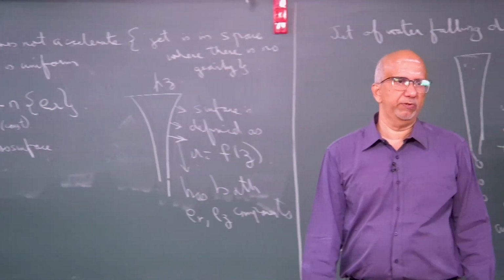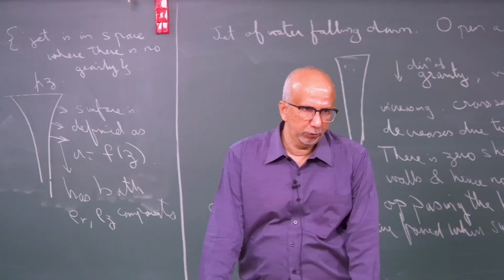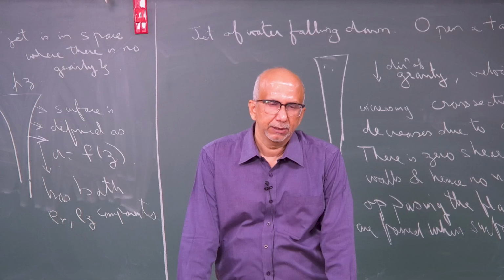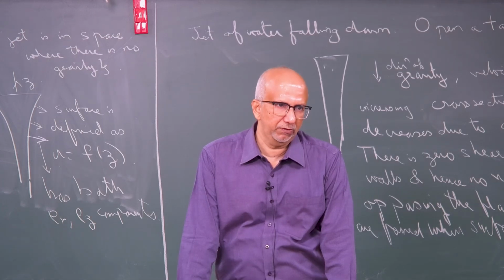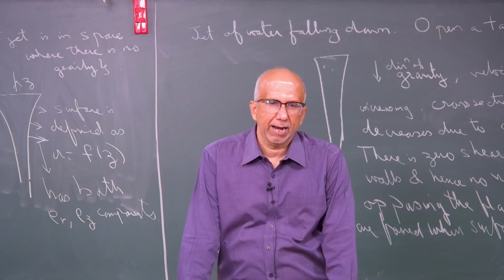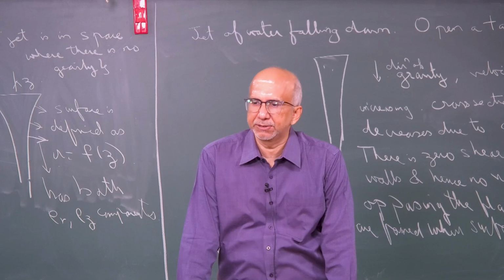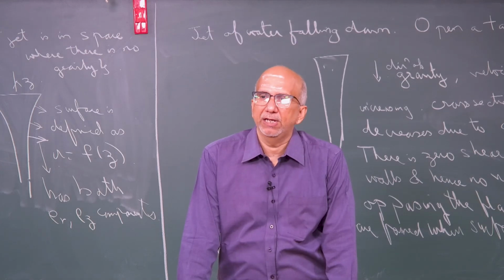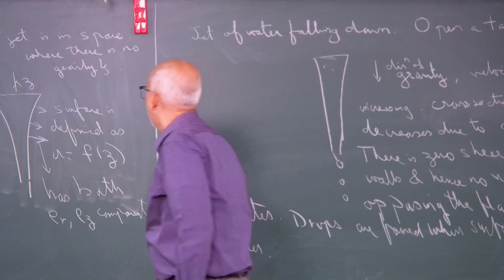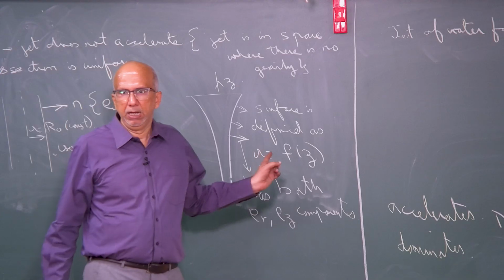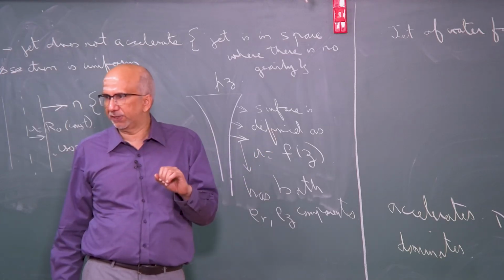What we want to do is understand, because when you have a surface of this kind, you want to be able to apply the boundary conditions at the surface. Whenever you are solving a problem, you need to apply boundary conditions. These boundary conditions have to be applied at that surface. And this is one of the areas where our formulation of n dot t is useful. How will you find the force on this surface? n dot t gives you the stress vector.